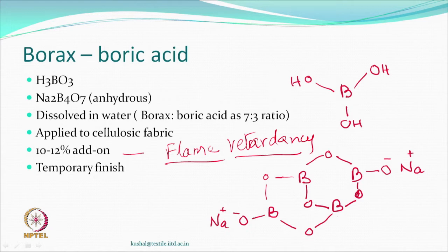It has been very successful. Anytime, anywhere, if you want, you can just mix them, heat it a bit, the solution will be there and you can apply, dry, and this is okay. So, when it is a dried fabric, when subjected to flaming, it is going to retard the flame. You may see the glow in this case, but the major part of the degradation process will be stopped. But it is a temporary finish, because no chemical covalent bonding reactions are expected in this. So, every time you wash, apply this again, and one can be safe.